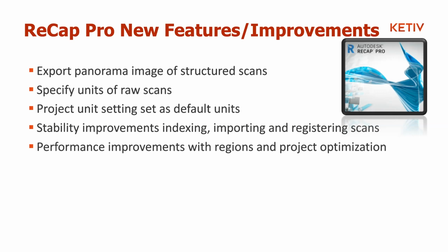And performance improvements with regions, so if you have a large number of regions in a project, and project optimization. Think of when you delete points out of a project, ReCap allows you to optimize. It's basically erasing the history and reducing the size of that project.